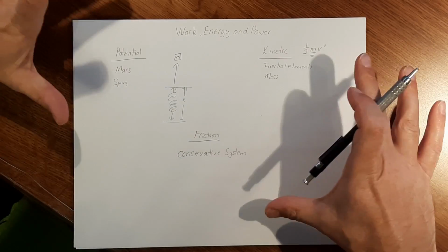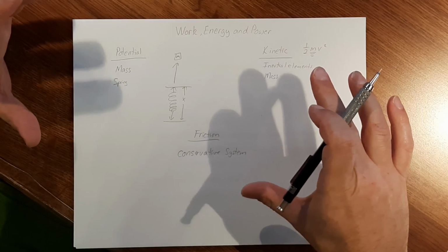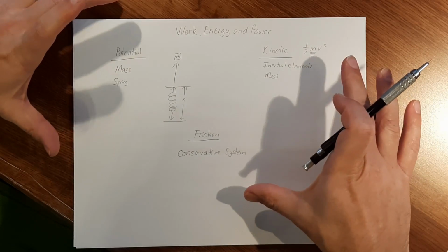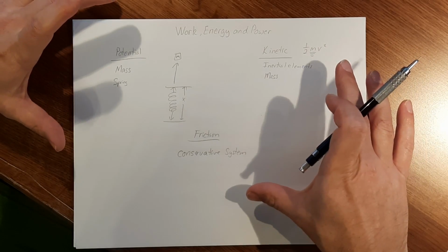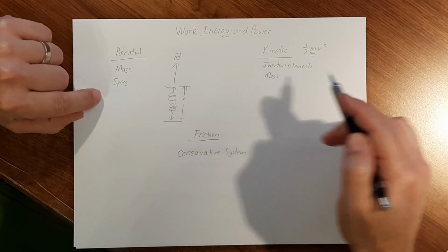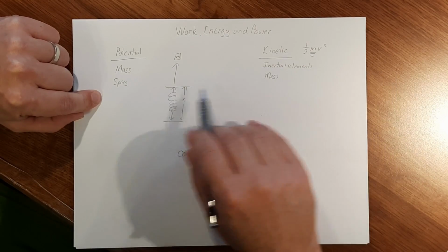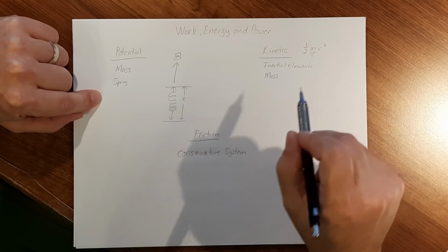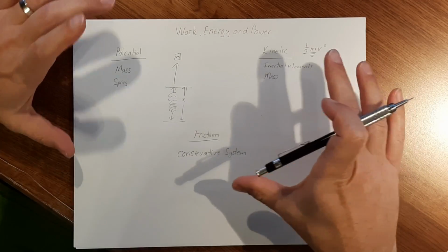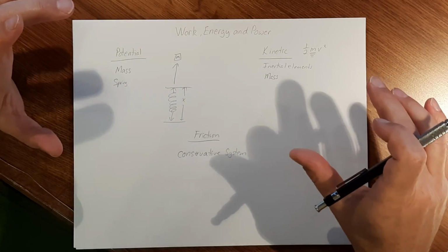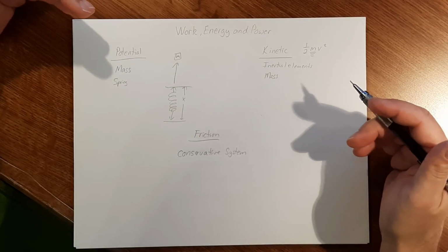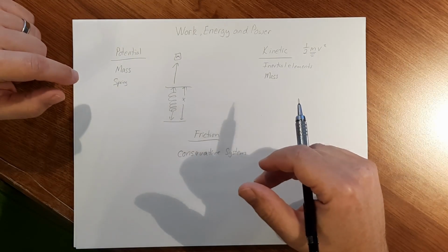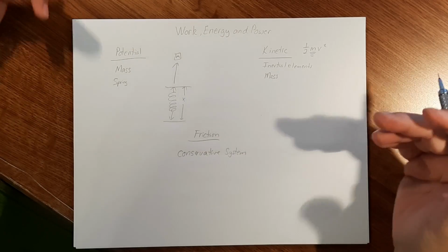So there you go. That's the basics of which elements within our mechanical system can store different types of energy and why they can store those types of energy. As you notice, the only basic element that we did not use is our dampener, B. The reason why is that dampeners actually remove energy. It can't store any energy, but it takes energy away from the system. And that's kind of how we work to get a stable system.